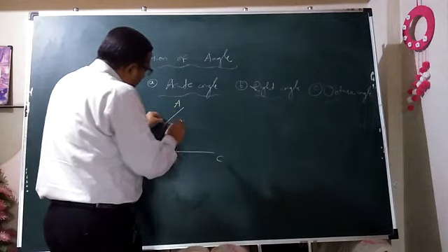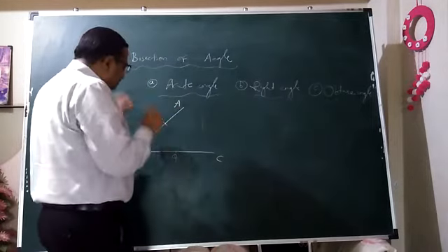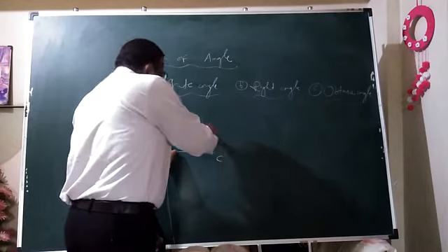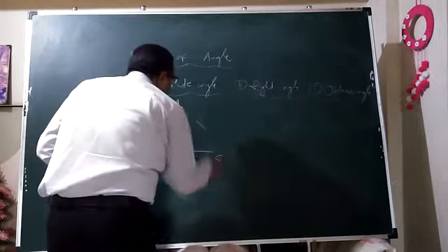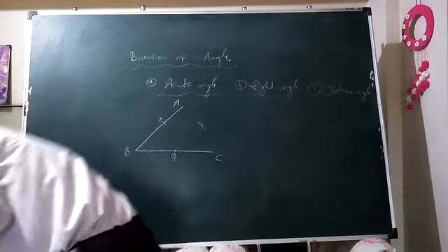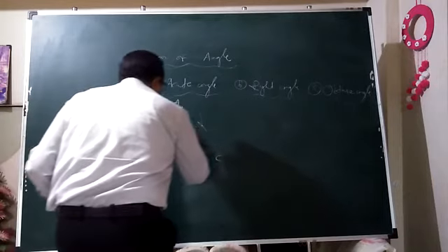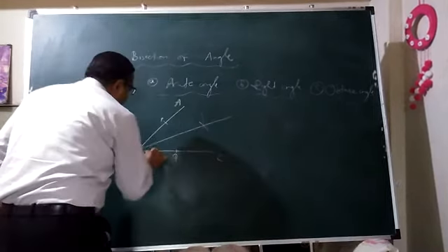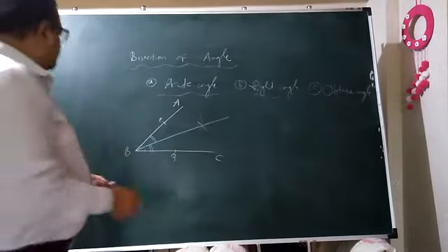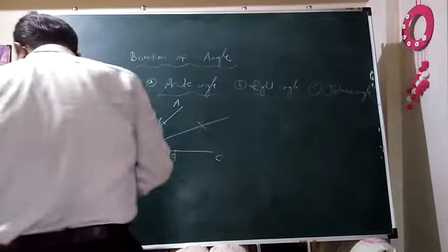Now we can change the distance between the legs of the compass and get two intersecting arcs. First from P as a center. Interchange the position of the needle, place it at Q, get an intersecting arc. So when we connect the intersecting point of both these arcs with B, it is going to yield us the angle bisection, that is the desired or expected solution. Both the angles will be of the same degree. You can check it by using a protractor. Okay, so this is the acute angle bisection method.